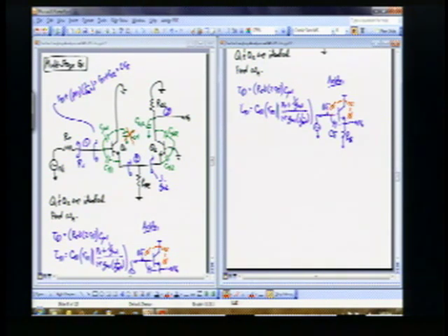So if that's the case, then you probably can neglect the time constant due to C pi. So if the gain V naught over Vi equals 1, then you can often neglect the tau pi naught, the time constant due to C pi.